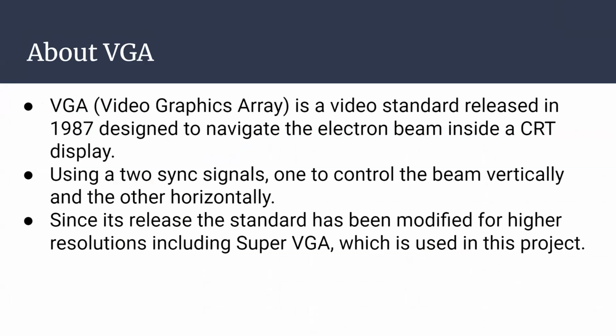So about VGA, it's an older video standard released in 1987. It's specifically designed to navigate the electron beam inside a CRT display. So utilizing 2 sync signals, you're able to control the beam vertically and horizontally.